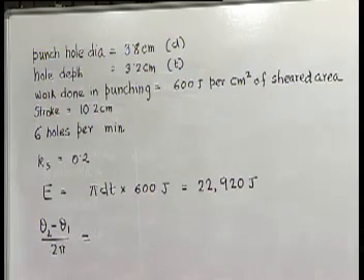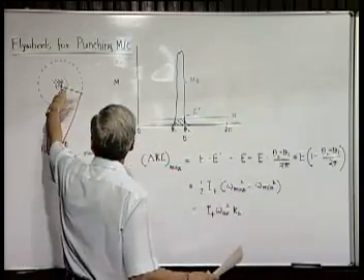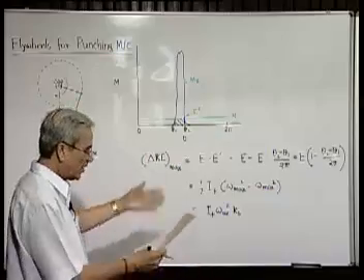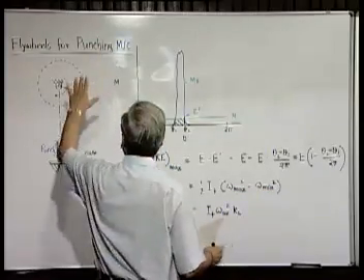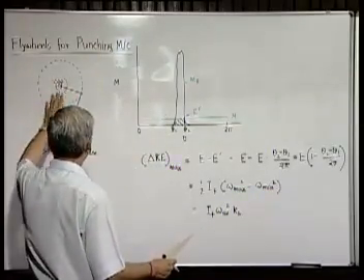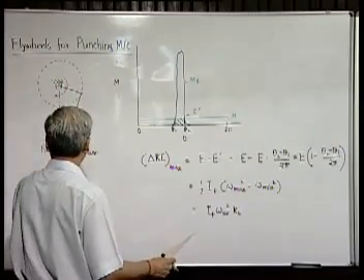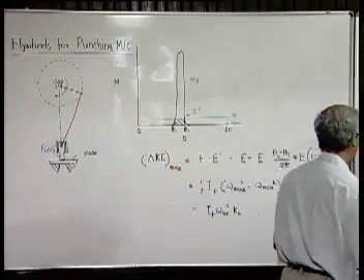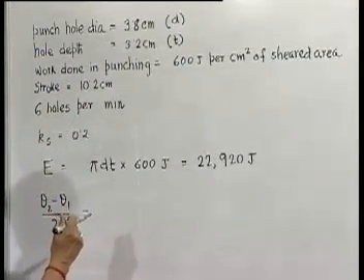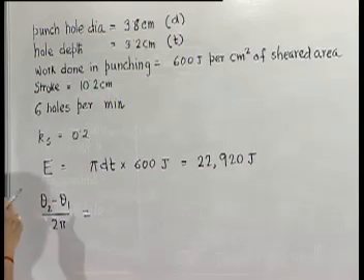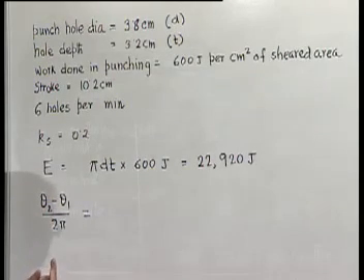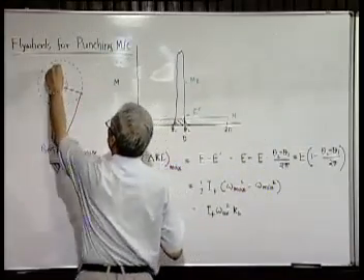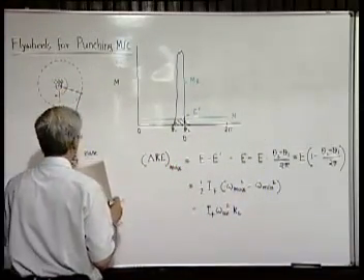Now this again, we can do a more accurate analysis by actually drawing the whole thing on a sheet. But otherwise we can also consider the movement of this whole thing to be linear, that means the speed and displacement bearing a linear relationship. If we do that, then the amount of displacement required for the punch during punching is T, that is the thickness, and the total length of movement, which is twice the stroke, 2s,